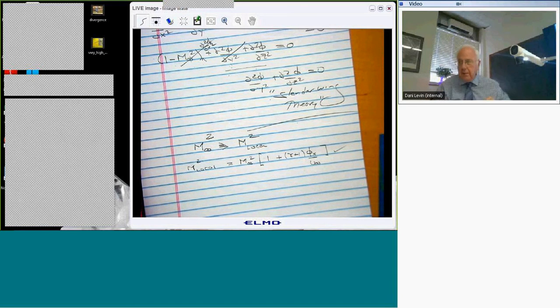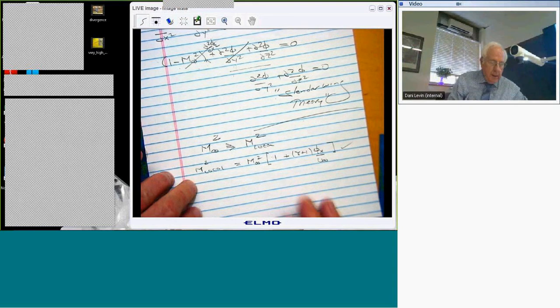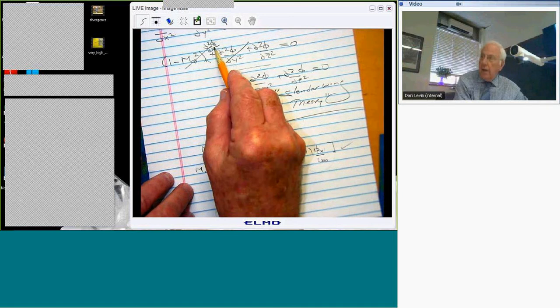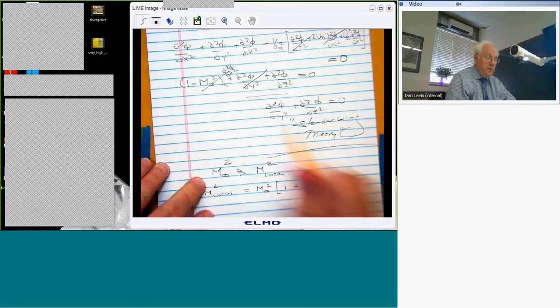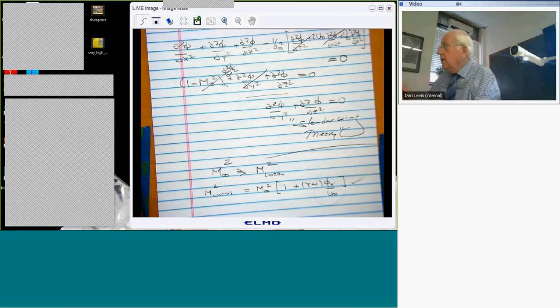But nevertheless, Zona, the company that produces Z-Aero, has something called Z-Tran, which is more or less trying to solve this set of equations. Okay. Now, what does this do mathematically? Well, when I multiply this term, which I almost left out, by that term, I convert a linear PDE into a nonlinear PDE. So all the usual analytical methods, Green's function, Fourier transforms, Laplace transforms,